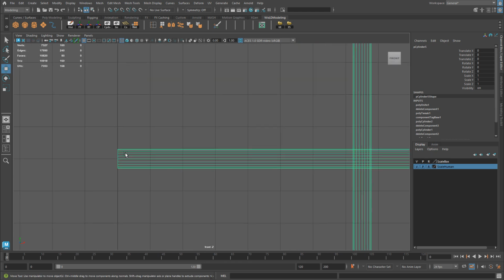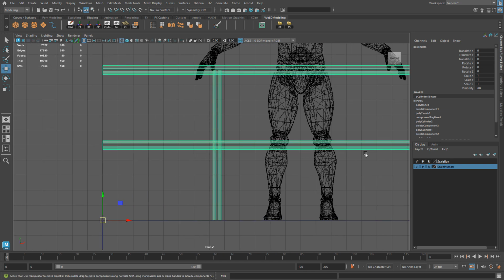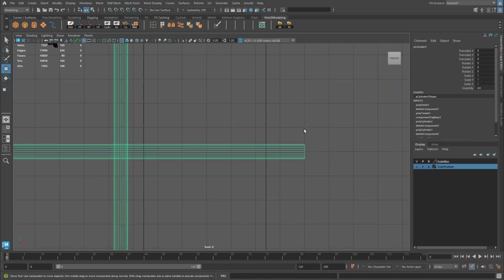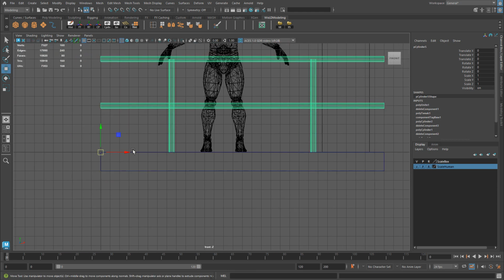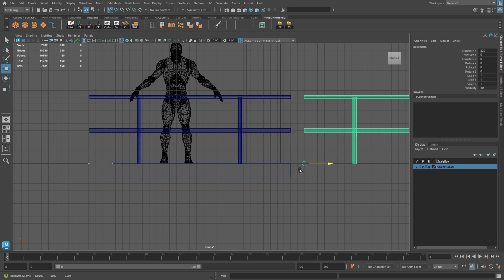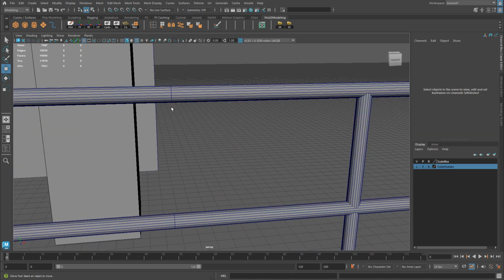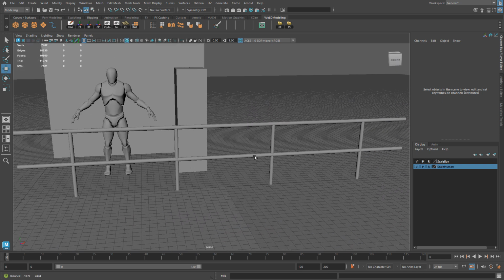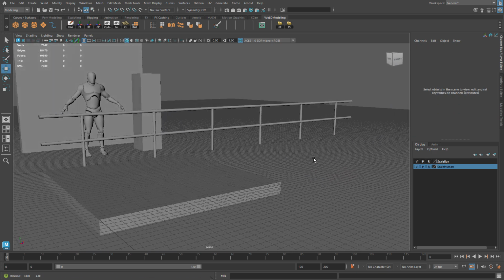The edges of these cylinders all align to the corners. It is 300 units in width. It matches to the other side, also matches to our floor. The pivot point is exactly here on the bottom. So if I take this and I duplicate it, hold V to snap to the grid and test to see if the modularity does work. And if there's no overlap, it will be flush next to the other piece. And this is exactly what you want. So I can just continue creating more of these across and they will snap to each other.